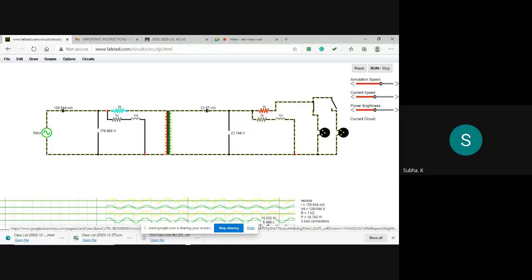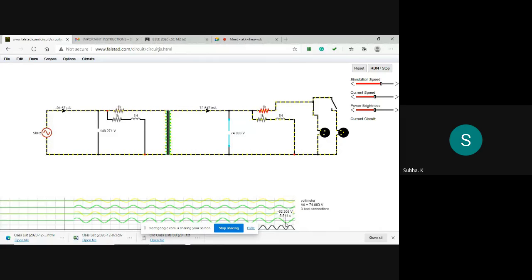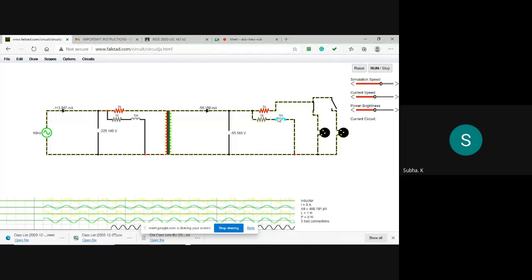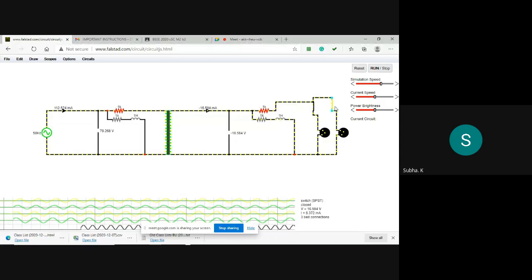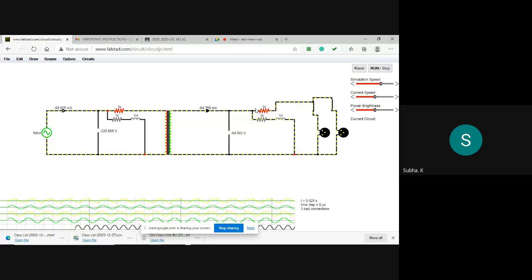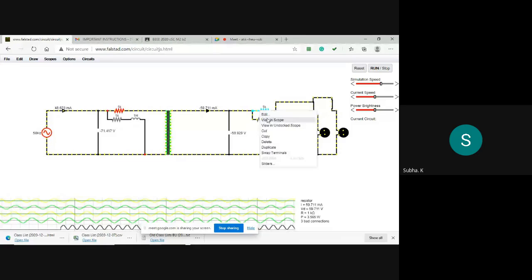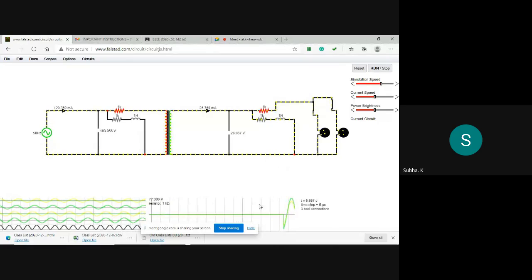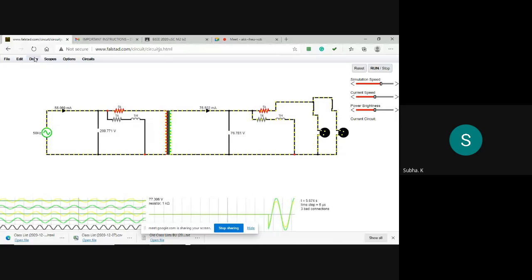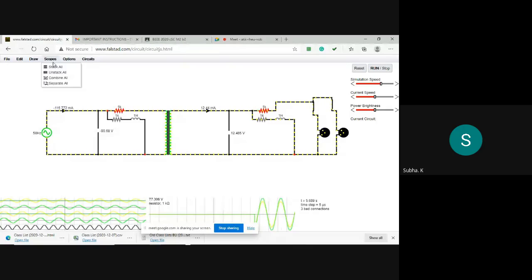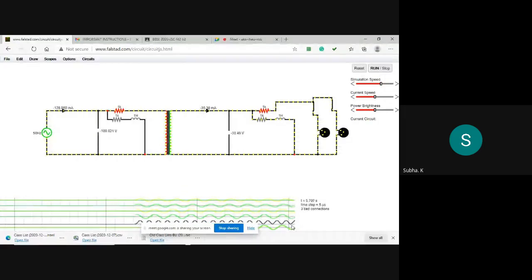That is 14.16 point something, it's showing, some watts, right? So that you can note down, and with that you can calculate the efficiency and power factor. Okay. One by one you connect loads. Here also you do the same thing. You view in scope, and stack all. The last waveform will give you secondary power.